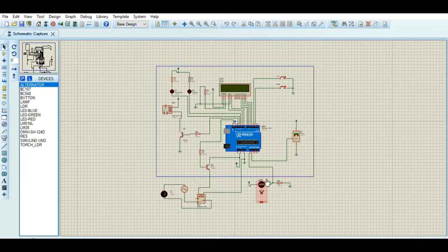We have the LDR sensor to sense the light intensity inside the aquarium, and the output will be the heater, the heating element, the LCD, and the lamp here. So as you can see here, I used two kinds of NPN transistor for the circuit. So we have a light sensing circuit and heater circuit. So let me show you my simulation here.